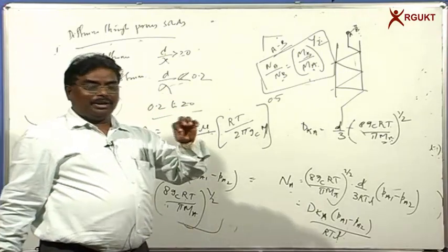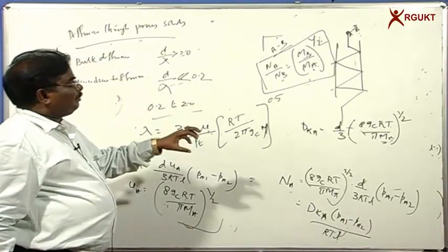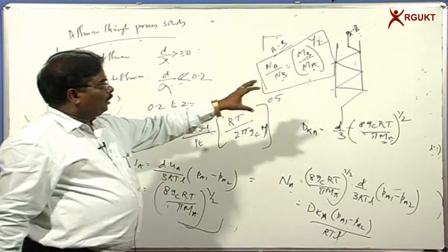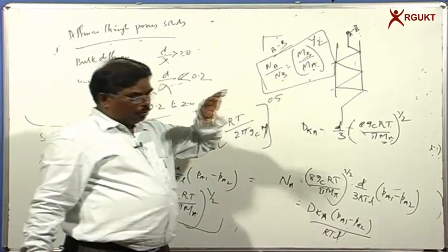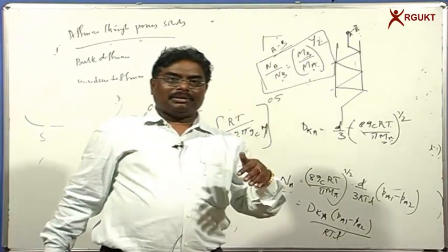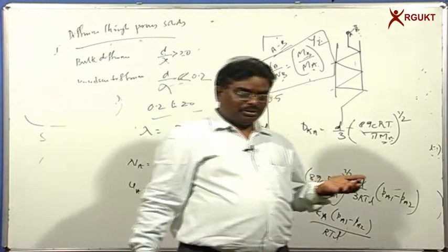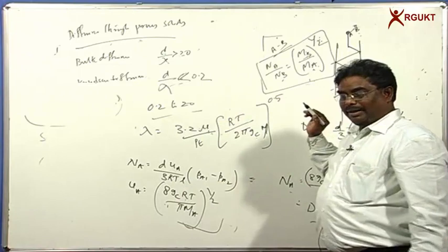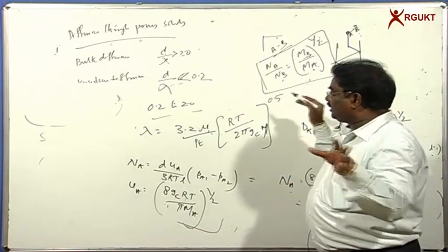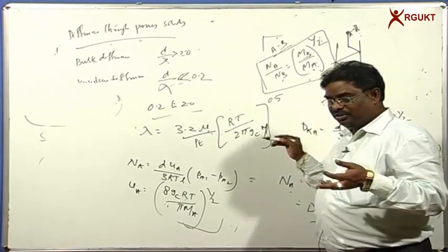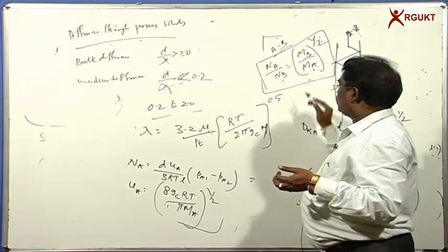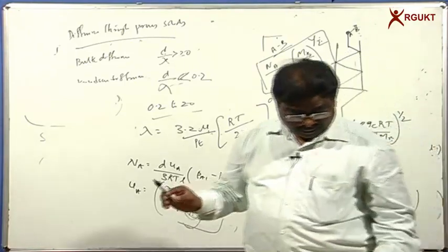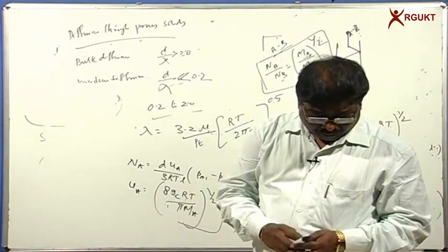That 1.014 is the most important parameter that attracted people to use gas separation by a porous membrane, where Knudsen diffusion takes place, for the separation of uranium 238 and 235. They use multiple stages, where more than 300 stages are used for the separation of uranium isotopes. So this is the most important thing that I want to talk to you about.